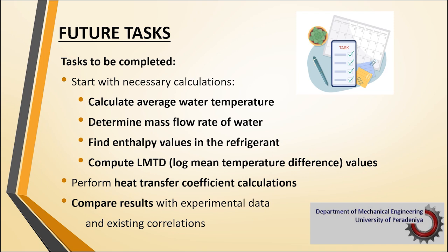Moving forward, my focus will be on completing several key tasks. Calculate the average water temperature, determine the mass flow rate of water, find enthalpy values of the refrigerant, compute the log mean temperature differences, and finally, perform heat transfer coefficient calculations and compare the results with experimental data and existing correlations.